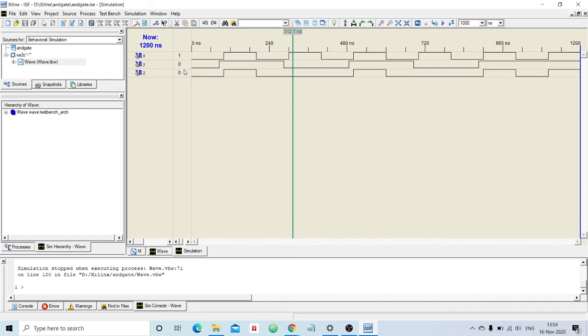Okay, now either you can use the previous way that I said, or if you find difficulty in that way, you can go for this. Like this, you can vary this. At this point, what is the x value? It is 1. What is the y value? It is 1. If both are 1, what should the AND gate output be? It is 1, right? Okay, at this point, x is 1, y is 0. For 1 0, the AND gate should produce 0.